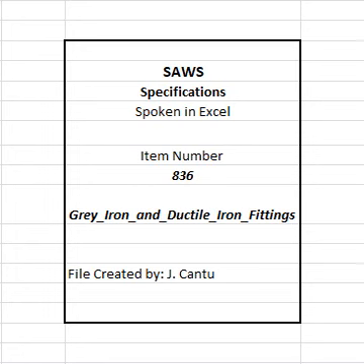D. Calculations and limits of thrust restraint shall be based on AWWA M41 or DIPRA thrust restraint for ductile iron pipe, latest edition. E. Class and length of joint. F. Submit manufacturer's certifications that ductile iron pipe and fittings meet provisions of this section and have been hydrostatically tested at factory and meet requirements of ANSI A21.51. G. Submit certifications that pipe joints have been tested and meet requirements of ANSI A21.11. H. Submit affidavit of compliance in accordance with ANSI A21.16 for fittings with fusion bonded epoxy coatings or linings.